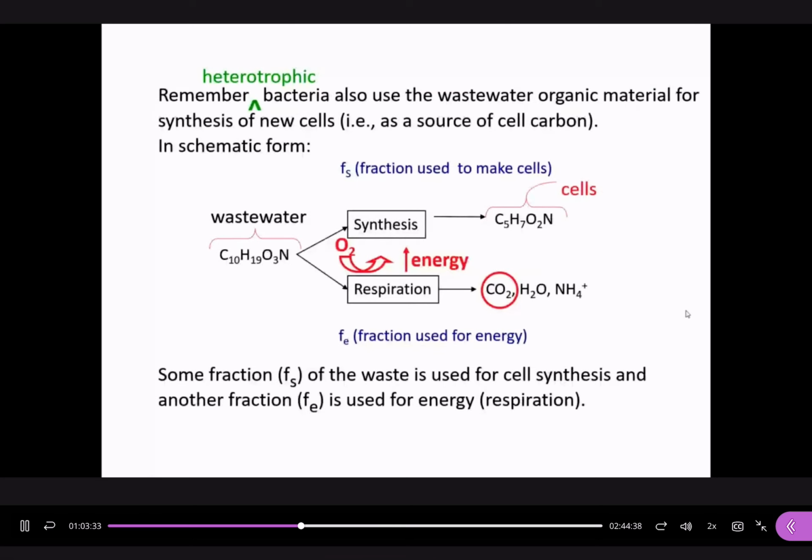And this is cells. Last lecture you calculated the theoretical COD of cells. Does anyone still remember the number? Theoretical COD of cells. What is a cell? C5H7NO2, right? We use this chemical formula to represent bacteria cells. What is theoretical COD?